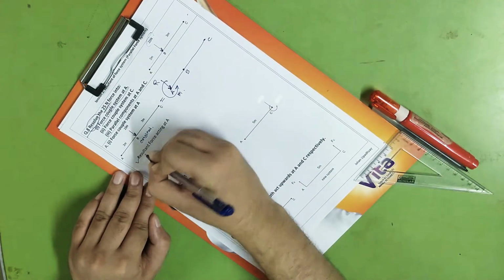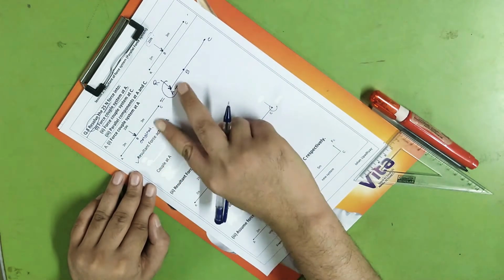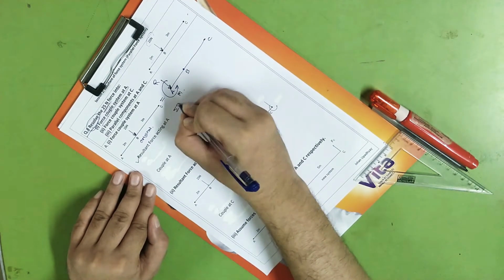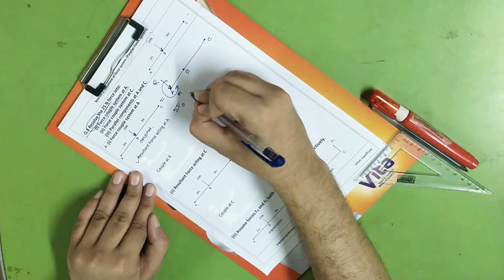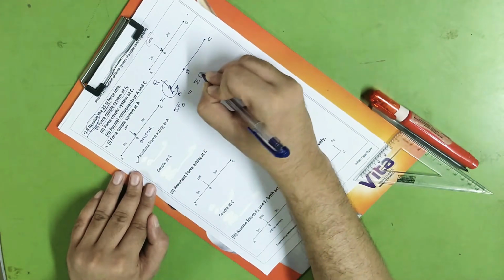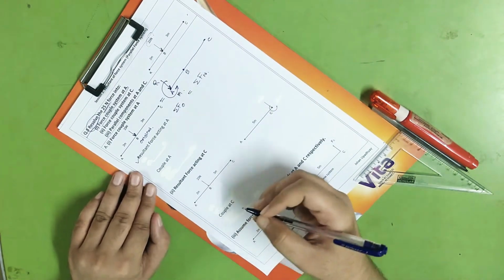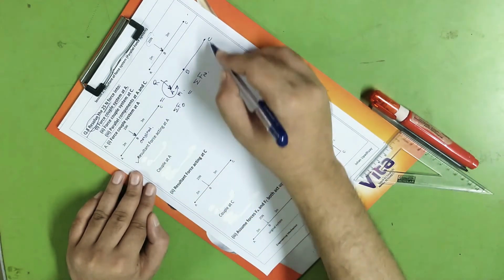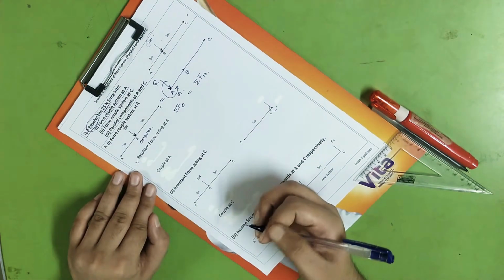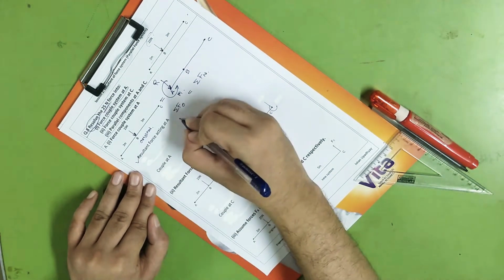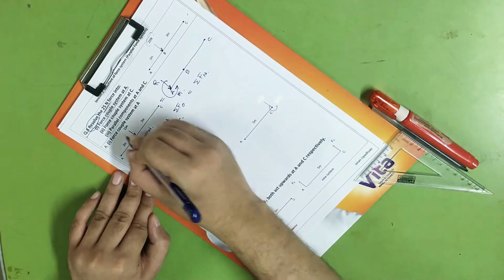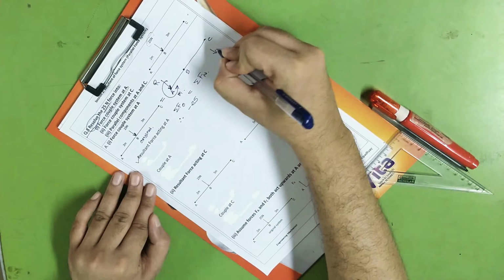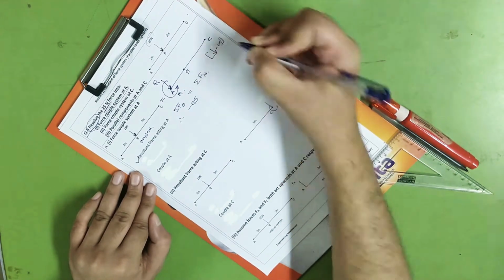Let us first start with the resultant. When I am saying that these two systems are producing the same effect, can I say that the summation of force in the original system is equal to the summation of force in the new system? So whatever total forces are acting in the original system must be equal to the total forces acting on the new system. With that, first for the original 25 Newton, I'll say minus 25 Newton, because here again I'm assuming downward forces are negative.